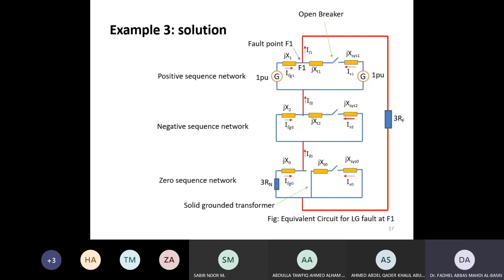And the zero sequence impedance of the generator is normally also lower than the positive or negative sequence impedance. For the transformers and the system, we also need to know the negative sequence impedances. So this is the negative sequence network without sources, same as positive without sources.